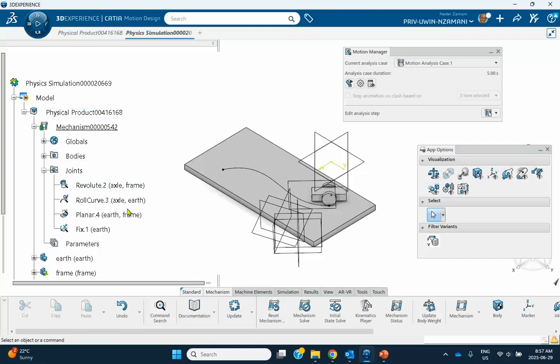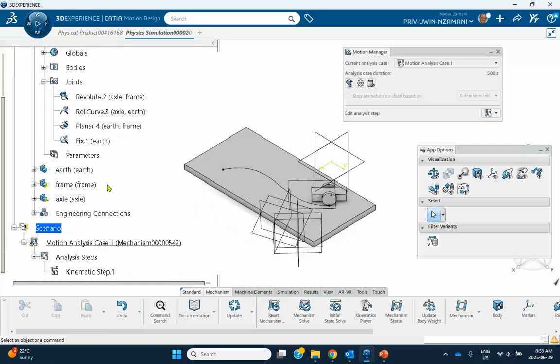What I'm telling you is that, first of all, if you're trying to do the planar joint in motion design, it won't let you just pick those two, the plane and the top face. It expects the plane to have some face on it. And this is why tutorial 12 is important if you go that route. That's pretty much it. So, yep.